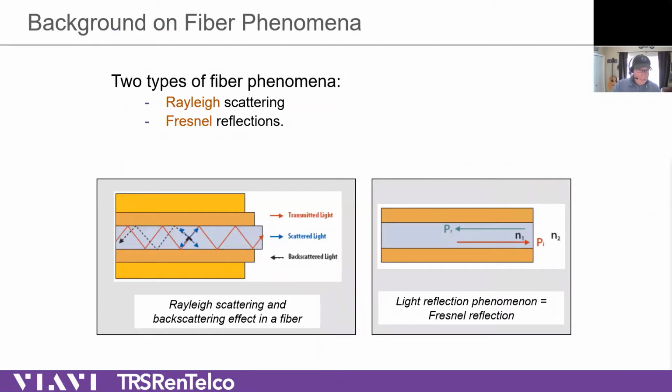Great, except when you bend too much. Right? So one of the number one principles when winding fiber is knowing what the minimum or maximum bend radius is before that refraction becomes a problem. I'm going to burn through this slide real fast. For those who like theory of how an OTDR works or light works, look up Rayleigh scattering and Fresnel reflections. Those two phenomena, if you like Wiki or just Googling it, check them out. This is exactly what's about to happen when light goes through.